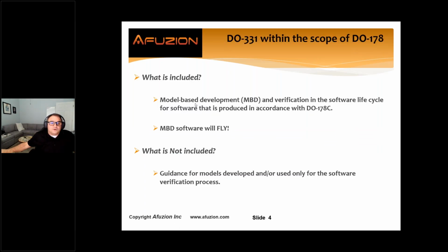So for DO 331, what does it include within the scope of DO 178, right? Specifically, it includes model-based development and verification of software within the lifecycle of DO 178. Your model-based development software, it will fly. It will be used on an aircraft.